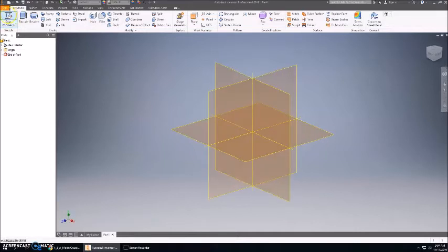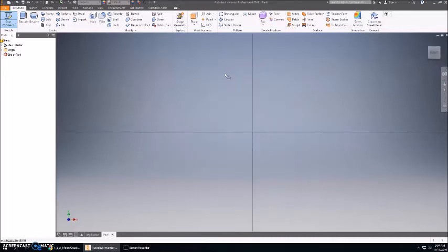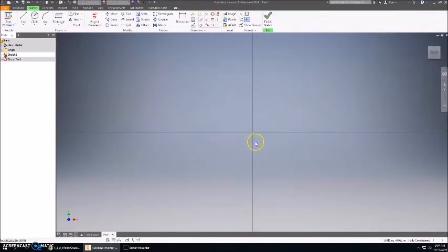So I come up to this upper left and I choose Start a 2D Sketch. As you can see, I get this crazy yellow box, and these represent the different planes that we can draw on because we're working in a three-dimensional area. Now we're going to start on the XY plane because we're building out. So I'm going to choose my XY plane, and it's going to rotate and give me a center axis.